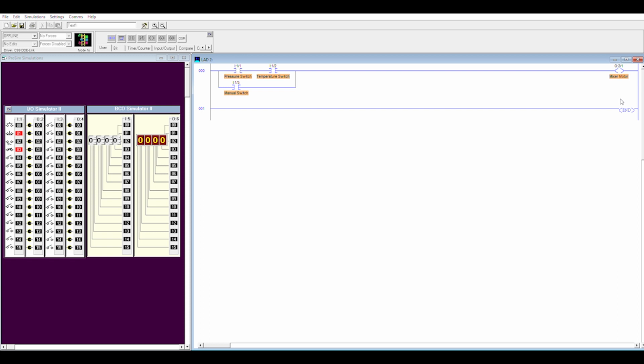So now I have built my first rung. Let's add a description to this rung. We usually like to know what it's doing, make it human readable. Why is it relevant to our process? If I go over the 00 and right click, I'm going to just edit a rung comment. Now usually in a large program, I'm going to have an intelligent comment, very small program here, but I'm just going to type in a small comment. This was our mixer process control problem.